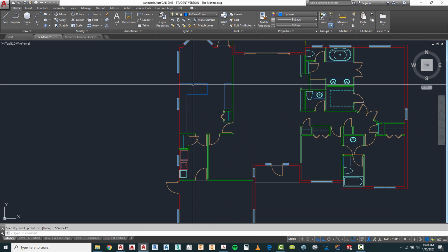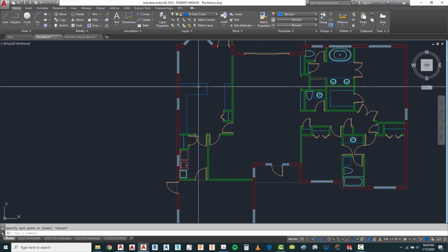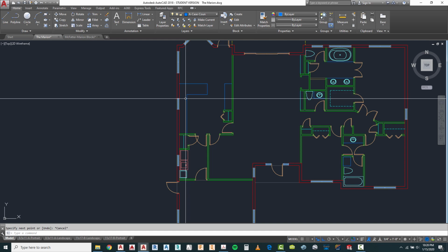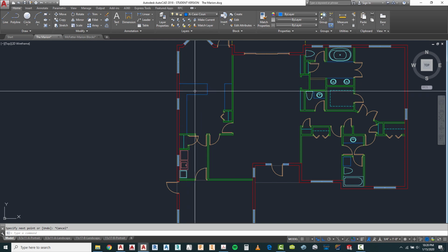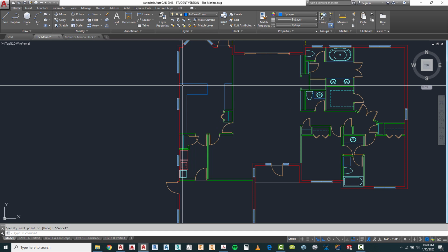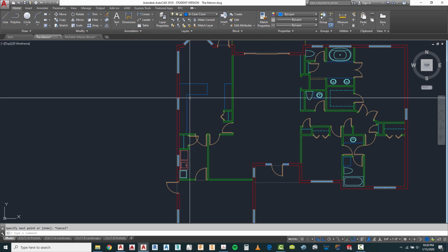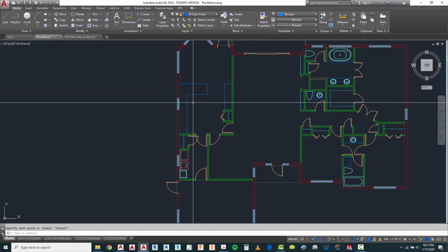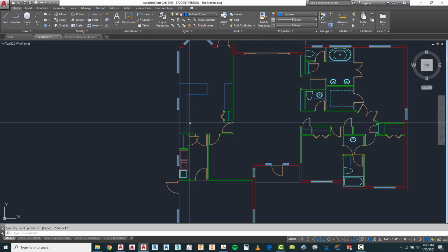This one is 3 feet as opposed to a 2-foot counter because there's going to be a hidden line in here that represents the edge of the cabinetry below, and then a 1-foot shelf located right there. So we may have to create a layer for A case hidden right in here, which we can also use for the above counters, for the upper cabinetry that we want to put in there. So let's take a look at how we're going to do this right now.